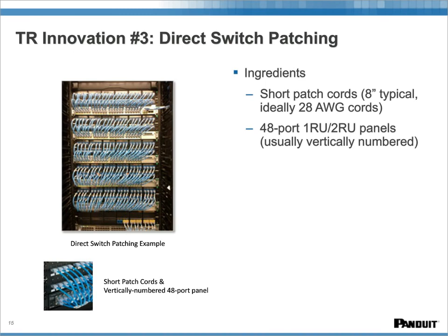Yes, PoE and PoE++, soon to be released standard. No pun intended, but it is a very hot topic, right? And I can tell you that absolutely 28 gauge patch cords, whether for 5E, 6, or Category 6A, will support the expected power levels in that range you just mentioned, Dan. We in fact at Panduit have a number of our own people who work within these committees, so we are well aware of the expected targets.